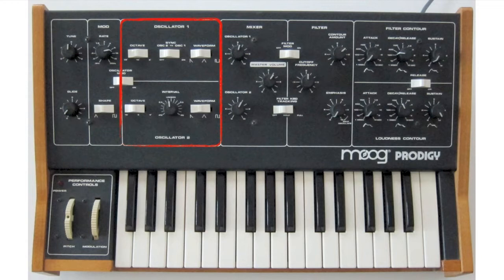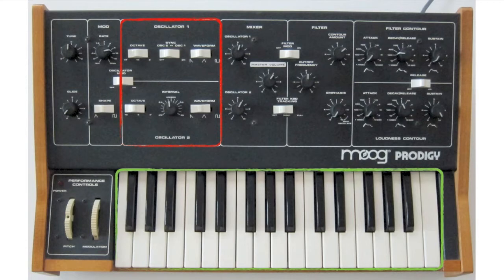For the first demonstration, I'll be showing you different configurations that can be used to modulate the VCOs. The keyboard is hardwired as a modulation source to the VCOs. The keyboard produces a voltage that increases or decreases at 1 volt per octave. Playing higher notes outputs a higher voltage, which increases the frequency of the oscillators.